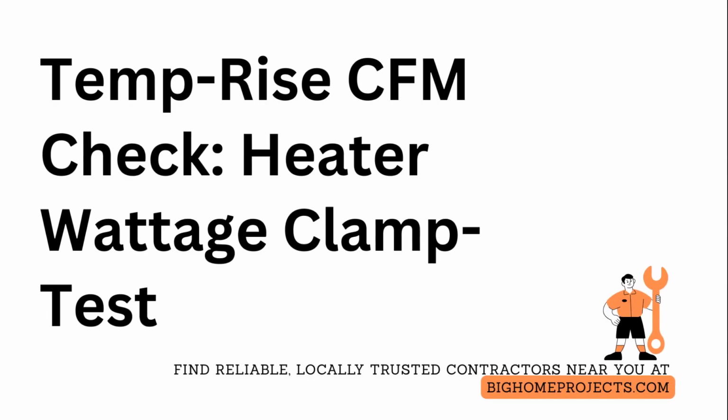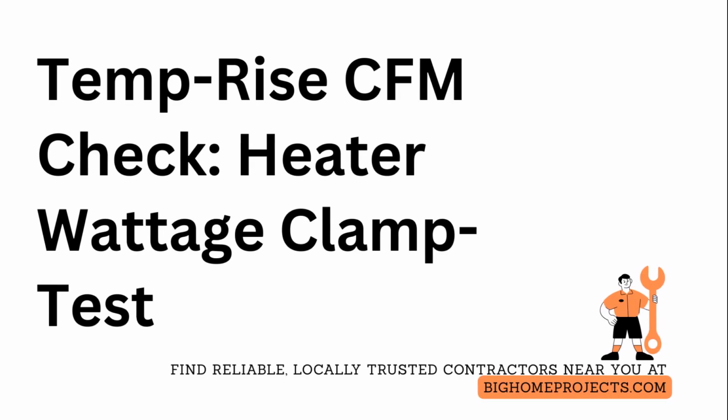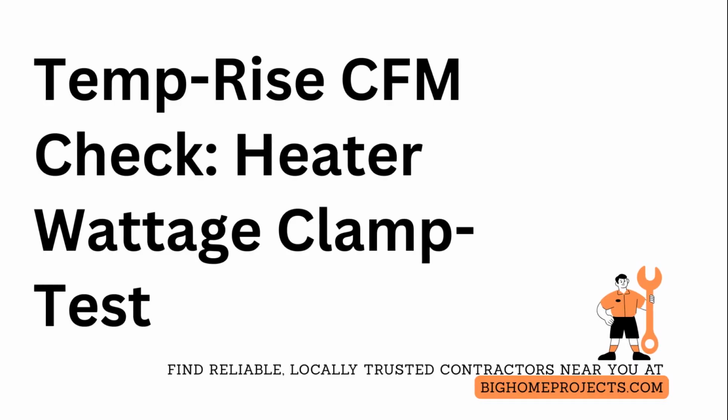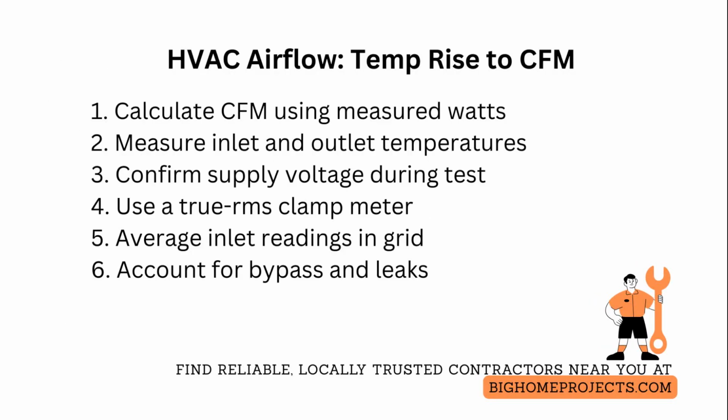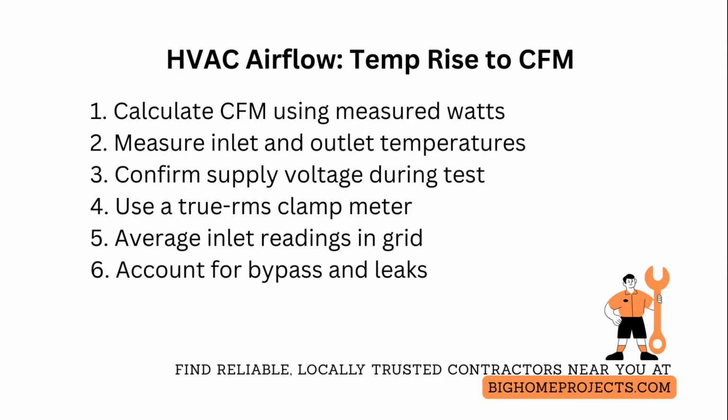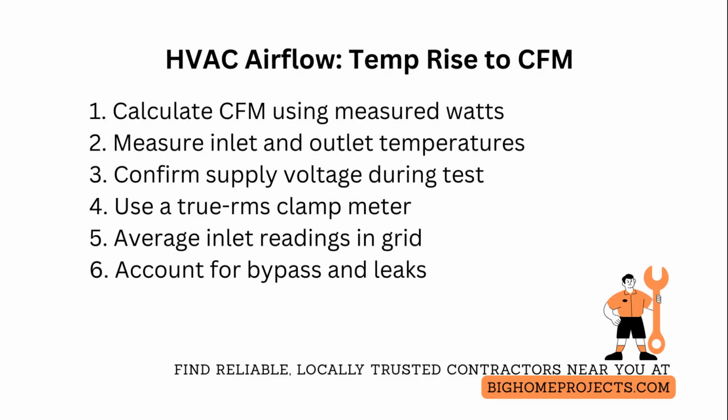HVAC temperature rise formula tells you how to measure airflow in cubic feet per minute by using the heater's wattage and the measured temperature rise across the heating coil. To measure airflow with expert accuracy, first calculate cubic feet per minute by using the formula CFM equals watts divided by 1,200 times temperature rise in degrees Fahrenheit, and always confirm the heater's wattage from the nameplate rather than panel